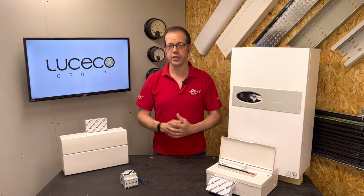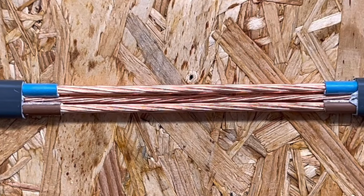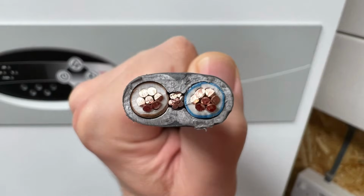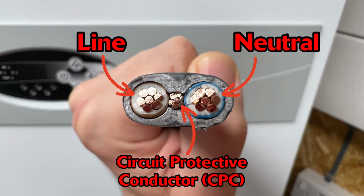Okay, so first things first, I'm going to be completely honest and say that I've deliberately used the wrong terms in the introduction for the conductors in this cable. In the context of supplying our 9 kilowatt Fusion Comet electric boiler from the electric heating company here, we should call them the line, neutral and circuit protective conductor, or CPC, because that's what they're called, and so that's what we'll be referring to them as for the rest of this video. We used the wrong words in the intro because very few people are searching for CPC sizes. Most will be using the term earth.